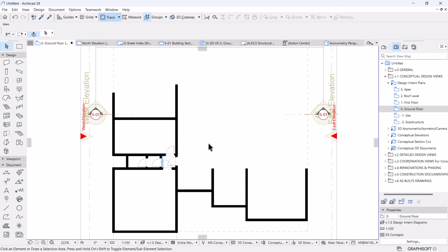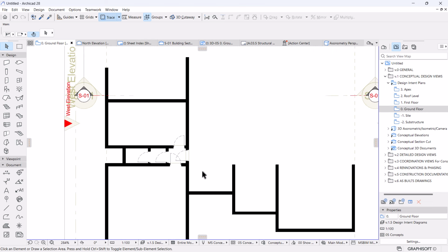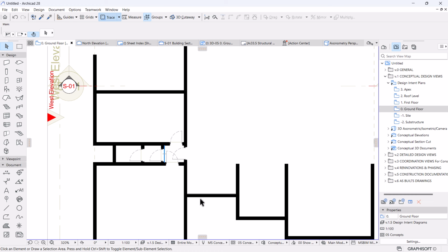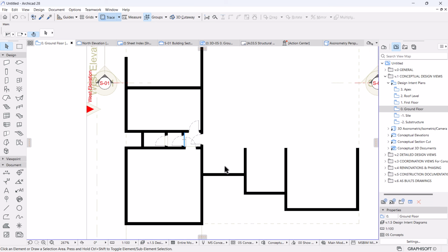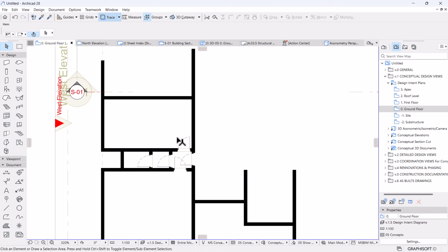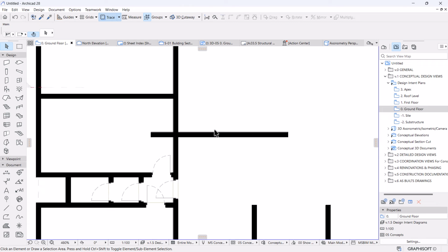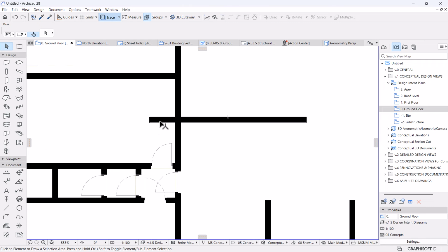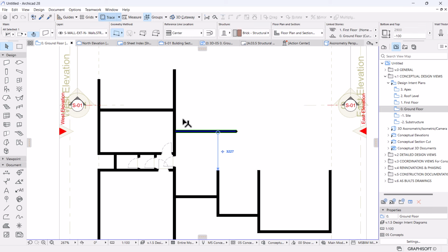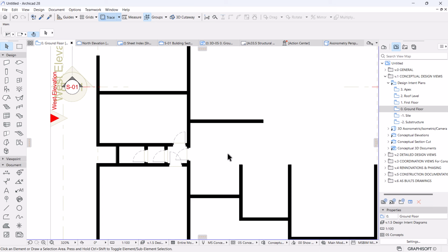Okay, so from here I want to move on to the right side, and so this will basically be the entry point of the building, right? And then from there we'll have a foyer that will have a bit of sitting around in the lobby. So I can copy this wall, place it somewhere there, and get rid of the door, trim it off there. And the positioning of it is very critical. Maybe let's make it 3 meters from the staircase. 3 meters from the staircase, yes.